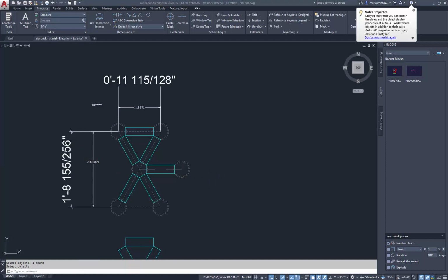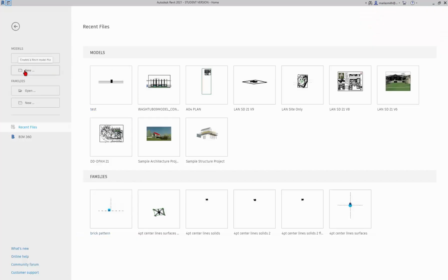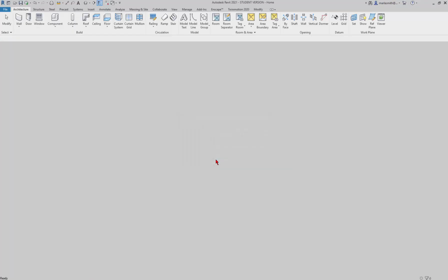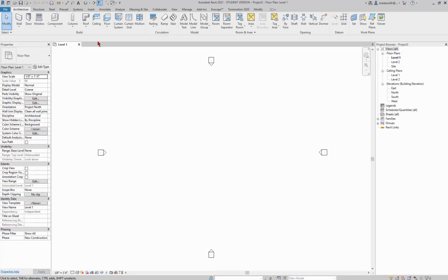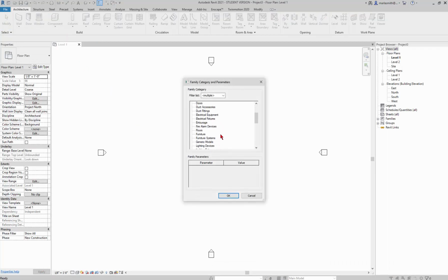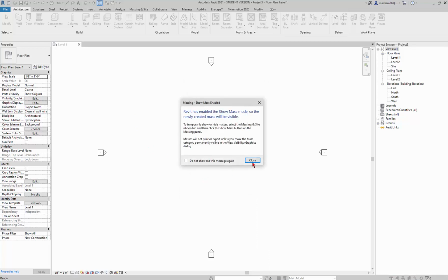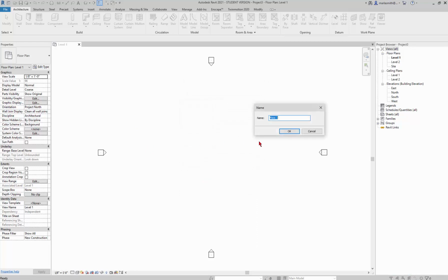All right, so let's go ahead and put it in Revit. So I'm just going to make a new model. This is one way to do it. We can talk about another way to do it. I'm just going to go to component, model in place, and I'm going to use a mass. This is the way that you should really put it in here, and it's really the only way to put it in a project without going through a family. So I'll just name it wall.